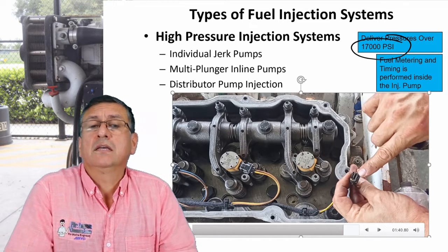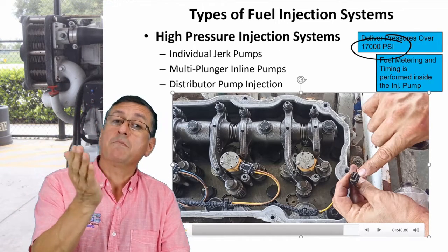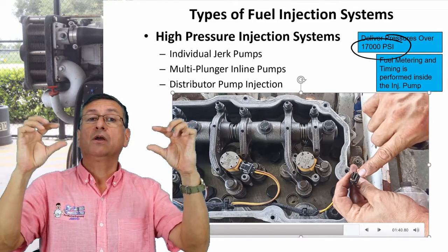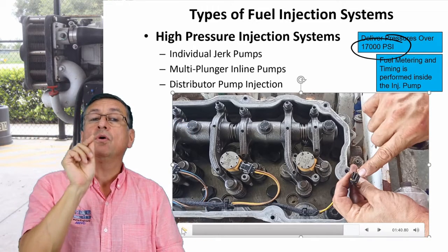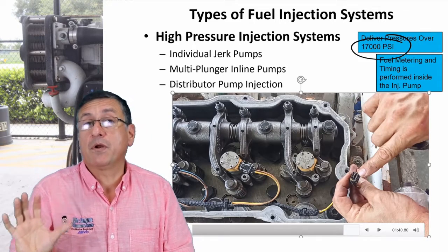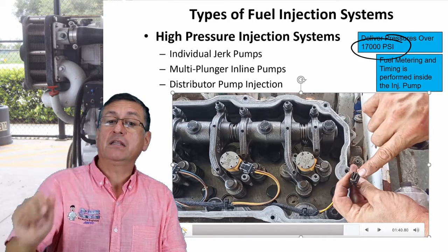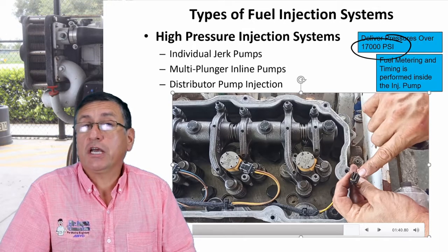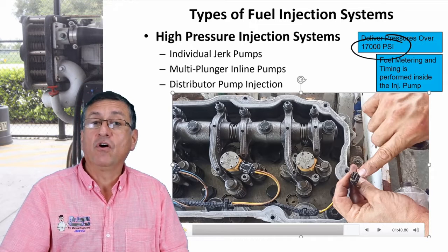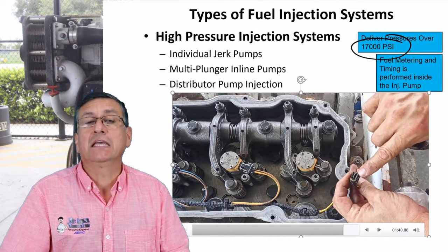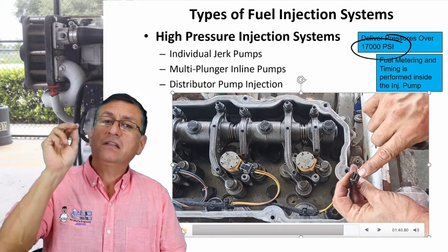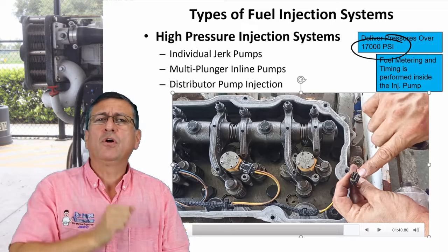If you check the service manual, you find the computer pins, and you can identify which pin is dedicated to each injector if you have a problem with one injector. I'm going to explain later the procedure to check each injector. Normally, each injector receives between 4.5 volts DC and 5 volts DC. If you have an external source of DC power, you can activate those injectors with 5 volts DC.